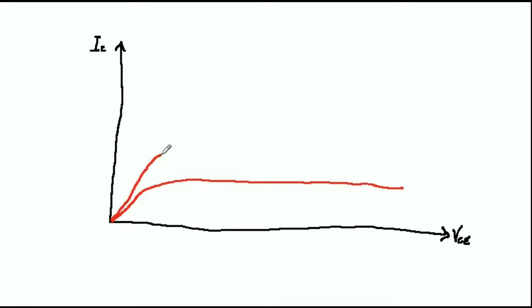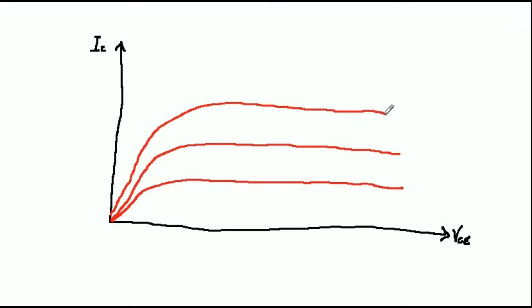Before leaving this simple amplifier, I'd like to use it to demonstrate a simple graphical technique which can be useful in understanding the behavior of lots of different types of amplifiers, not just transistor ones. This technique is called the load line. The load line is plotted on the device characteristic graph, which is shown on the screen for the transistor we've been using in the last couple of videos.